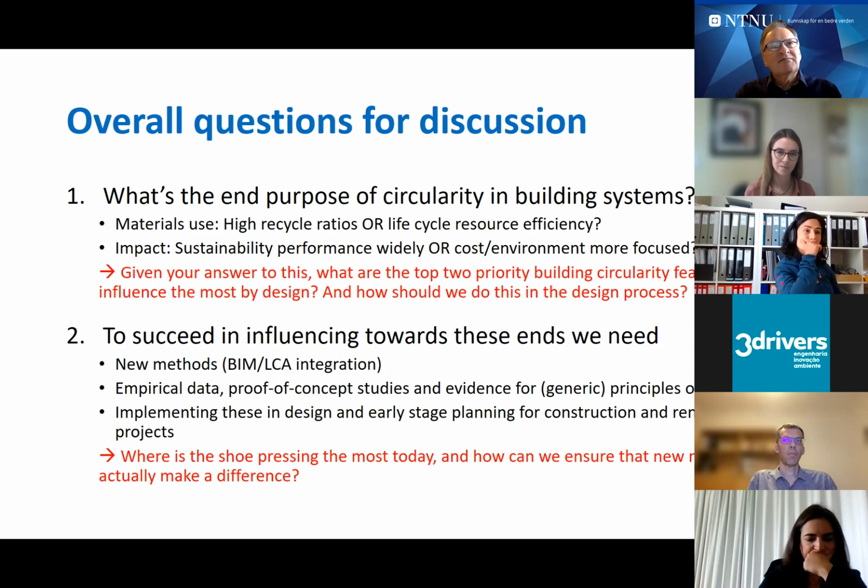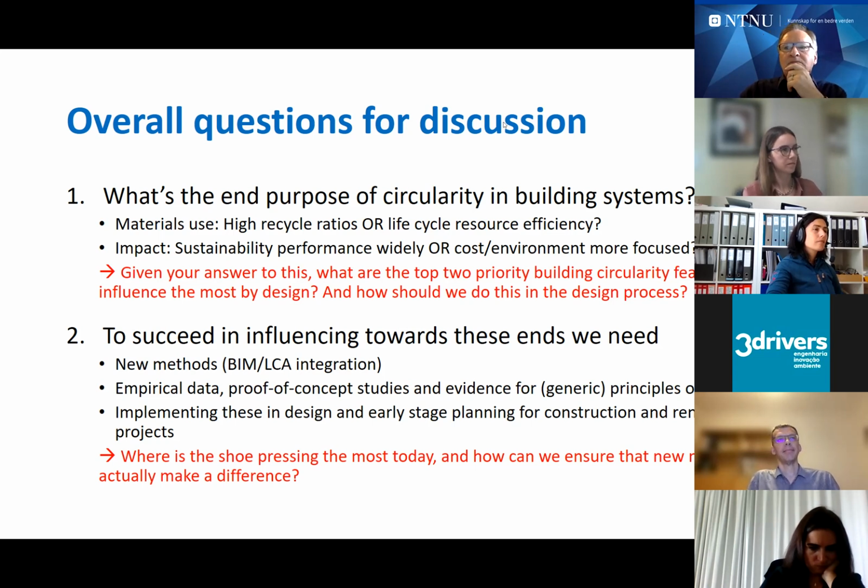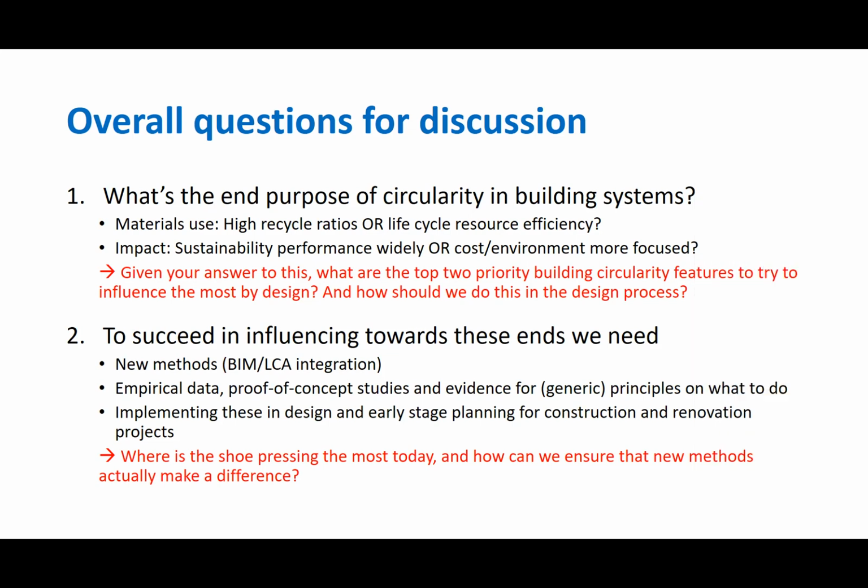For the integration, I think the most difficult issue in the method is the lack of data. When we want to integrate BIM and LCA, it's difficult because BIM is closed data, and we need to exchange the data between BIM and LCA, and there is no tool except IFC to help us exchange these data. Also, when we want to transfer the data from BIM to the LCA, we don't have any tool to help us with that. That's why we need to do it manually, or, like I said, the old way, using Excel. That's why we need to consider an integrated, developed platform that helps us integrate BIM and LCA.